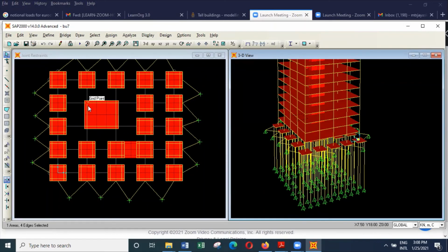So the chances of the drilling operation of one pile damaging the other pile is very remote because the gap is 2.4 meters. Whereas if you go with 2.5 times diameters with 1.2 meter, and when you deduct 1.2 meters, you still get a gap of 1.8 meter. So when you have a gap of 1.8 meter, the drilling operation damaging another pile is also very remote.